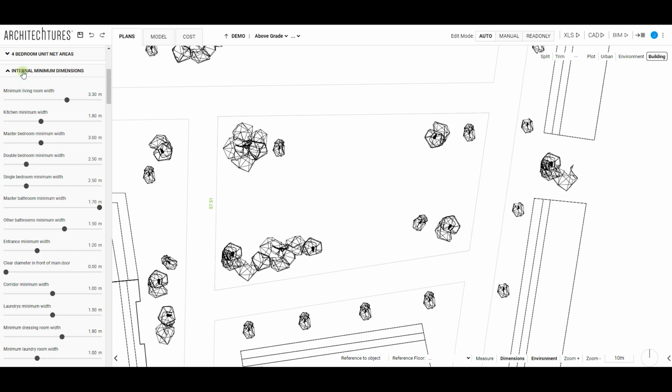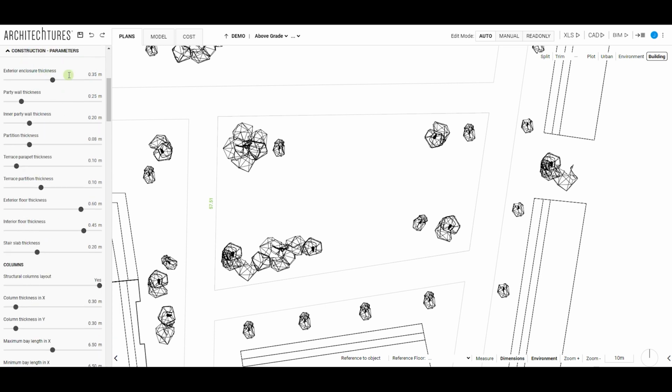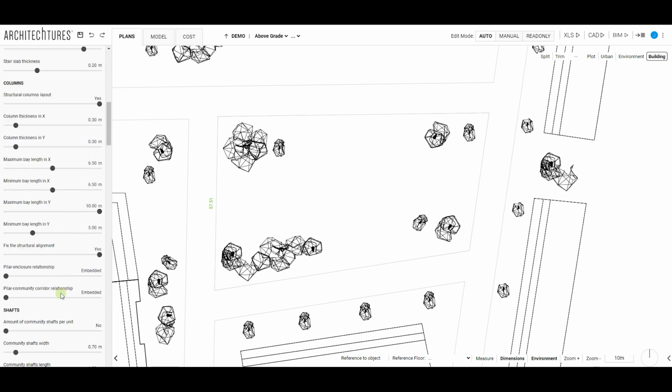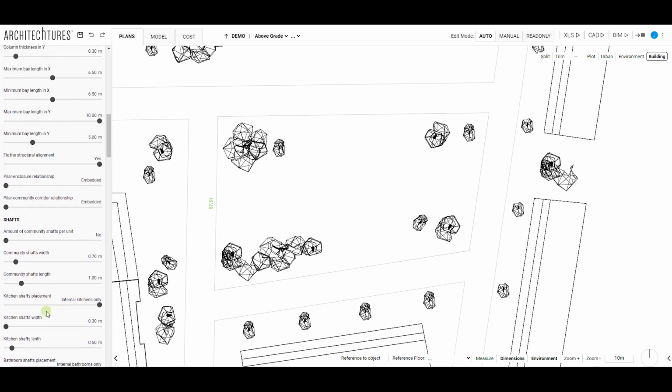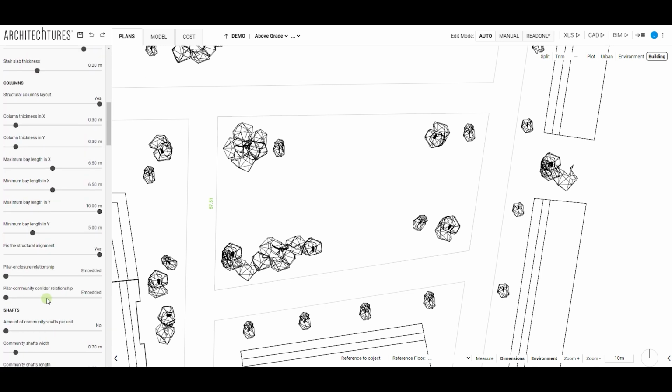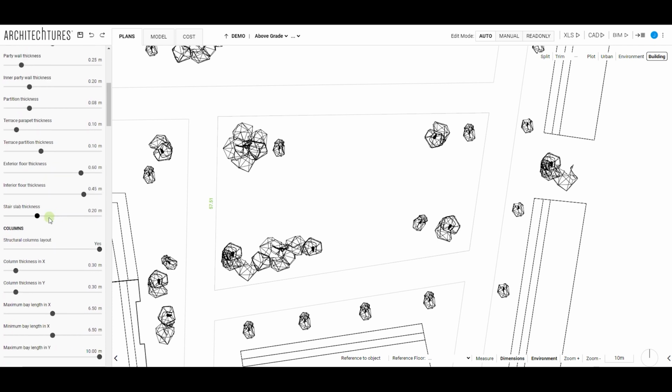The next tab is called Construction Parameters. Here, globally for the building, the thickness of the construction elements, both vertical and horizontal surfaces, as well as the distribution and configuration of structural pillars and ventilation ducts, are defined. The configuration of this section has a dramatic impact on surface calculations and efficiency ratios. Therefore, it is recommended to configure it before or immediately after creating the building.